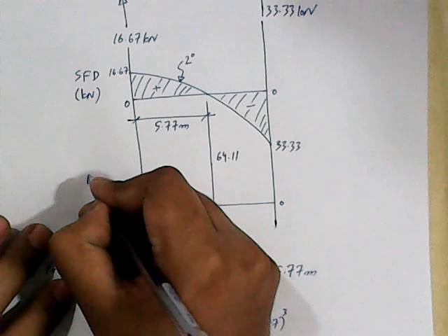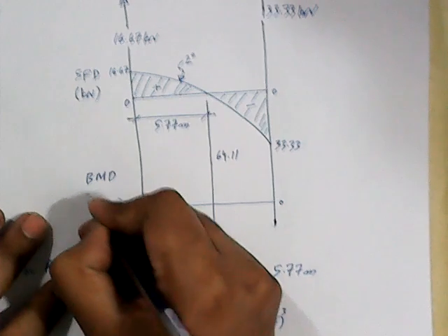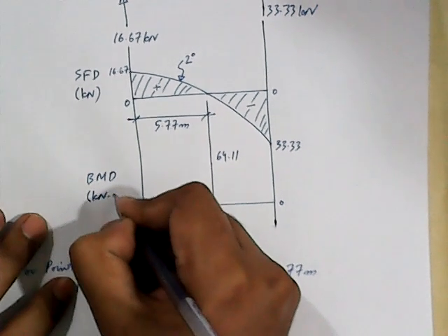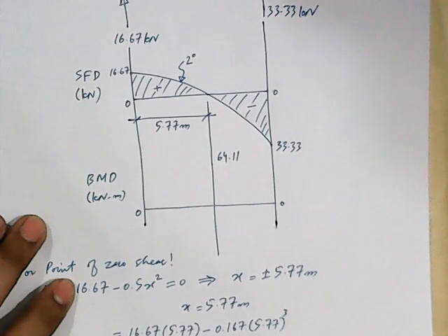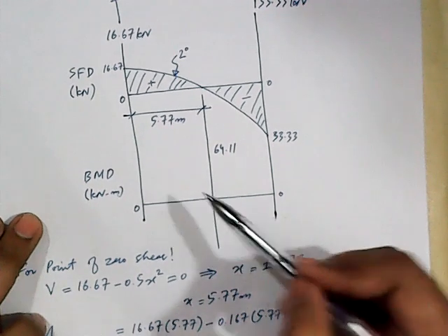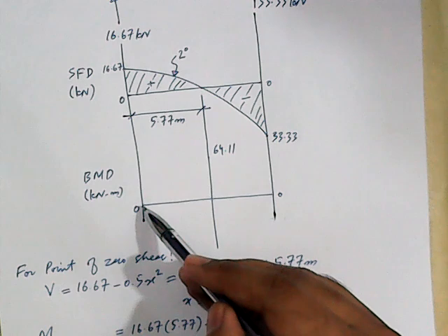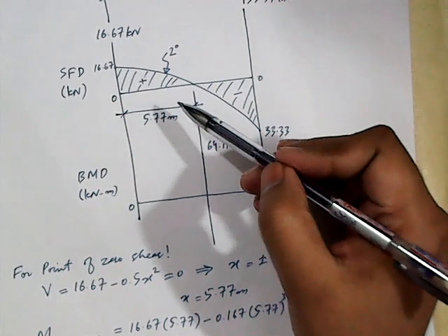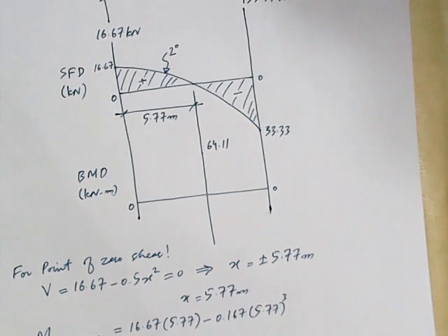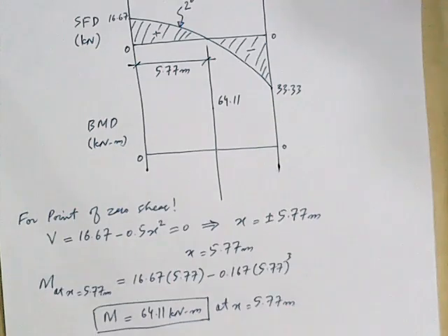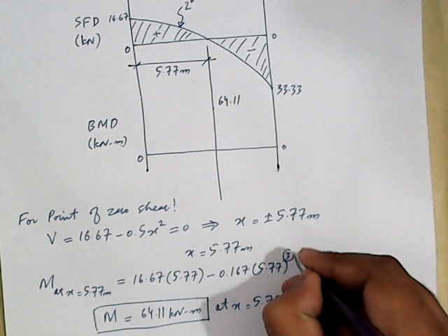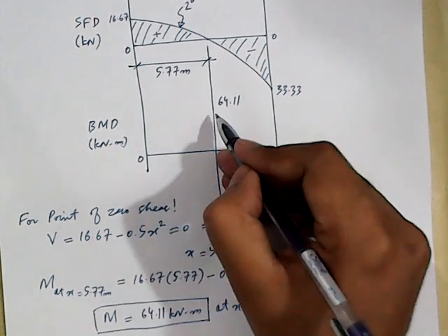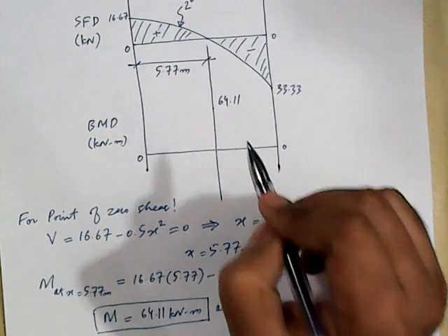We are drawing the bending moment diagram, and our units are kilonewton meter. Now again, we need to see how we should join this point with this point. For that, we look at the degree of the equation. The degree of the equation is 3. So these points will be joined together through a third degree line.